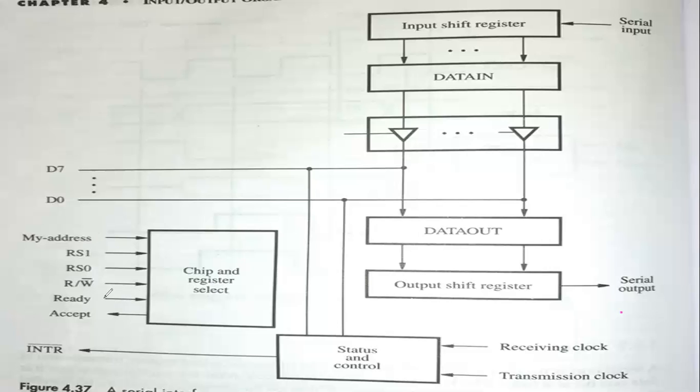Observe it very carefully. It is a ready signal sent towards what? Input or output. Whenever you are communicating with the input unit or output unit, first your processor should send the master ready signal towards them. Then they will react with accept, or slave ready exactly. But here, for that slave ready, we are naming it as accept, and for master ready, we are naming it only as ready. Clear? So all are having the same working principle as we discussed in the previous section.